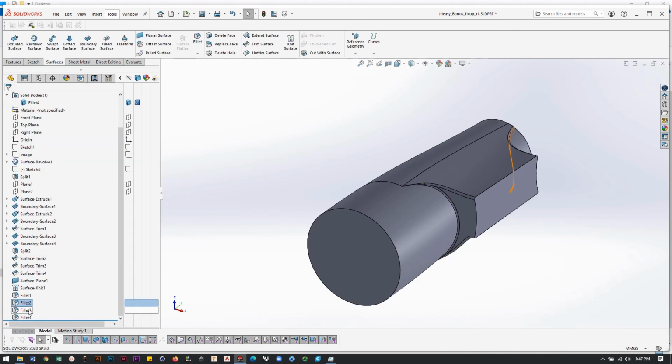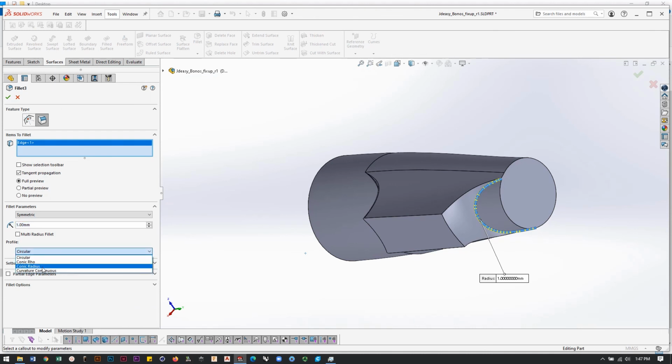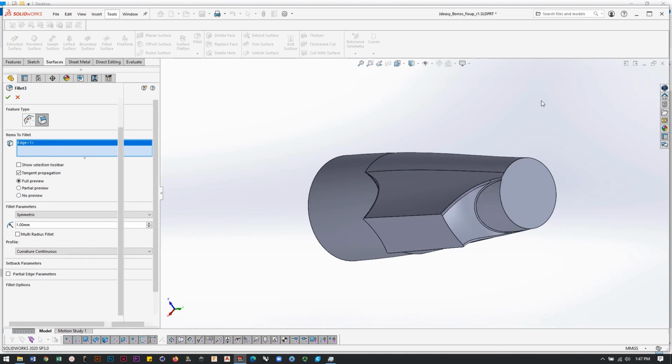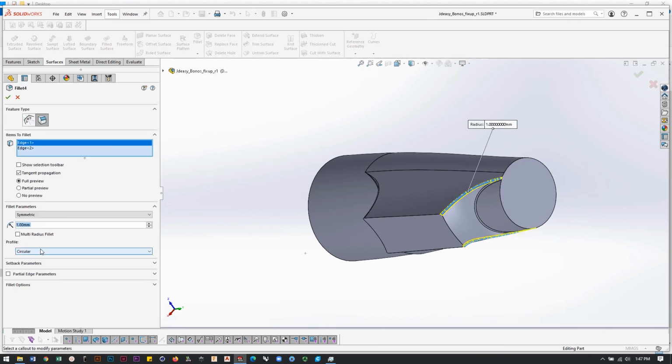This setting just takes the SolidWorks look away from your fillets. So really nerdy CAD people will look at your stuff and go, "You made that in SolidWorks? I can tell from the fillets." And if you set these to curvature continuous, then sometimes you can avoid that.